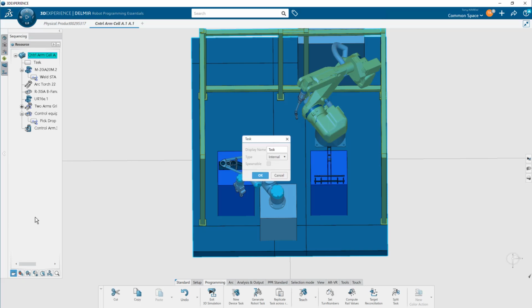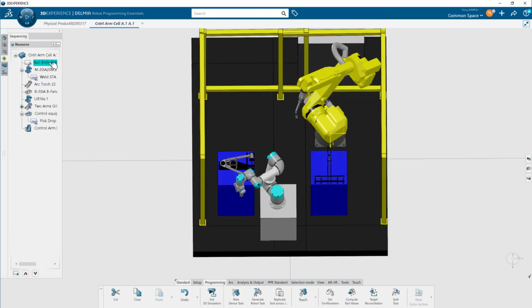To get the result I want, I could just create a task and run them both in sequence, and they'll sequence automatically. When the first one's done, the second one will begin. Make sure you make this a nominal task because it is a parent task and it needs to reference the children underneath it. So it must be a nominal task.